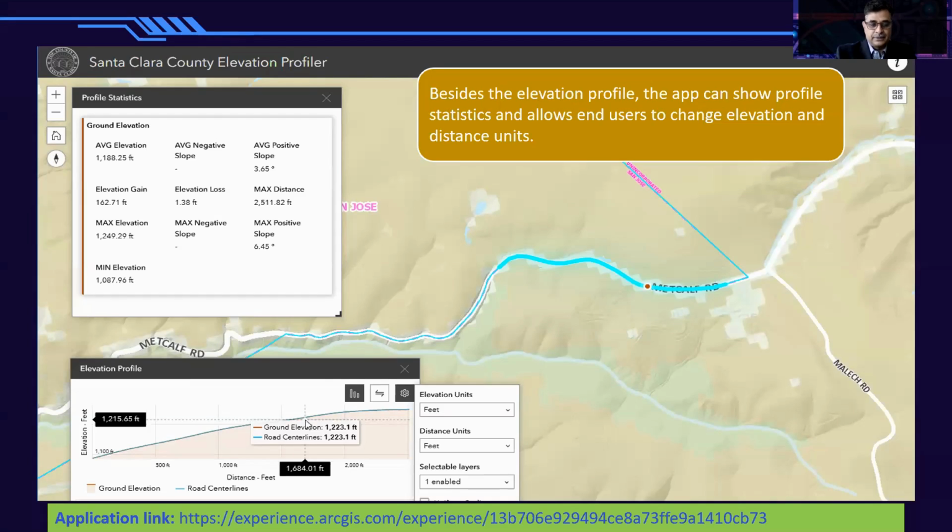Based on that, we can call around and see if any rental vehicles are available that can do that type of grade. And luckily we were able to find one, and we were able to complete this project. Without this GIS tool, it could take a long time because we have to look at some old survey data, and see if the grades have changed over the years, or getting a survey done for a long section of road like that can be very expensive.